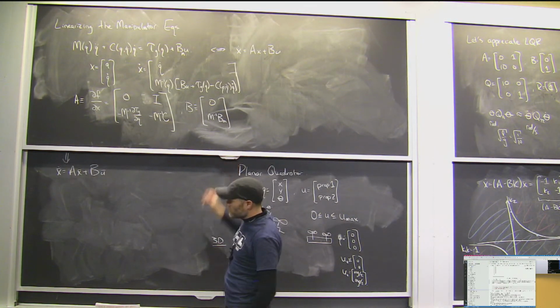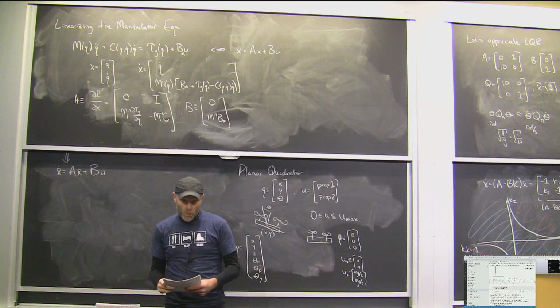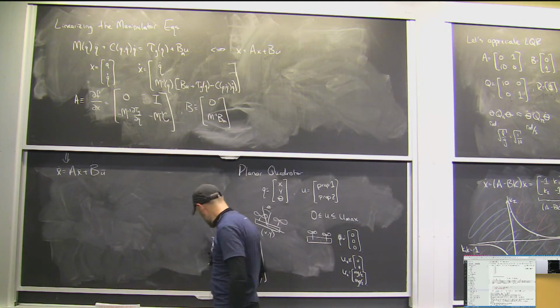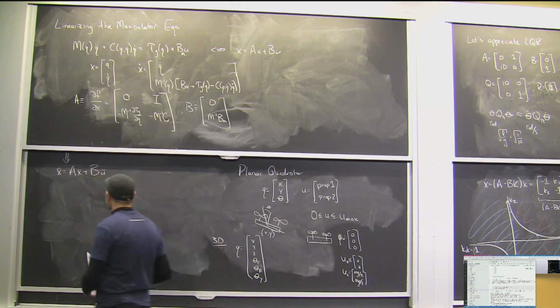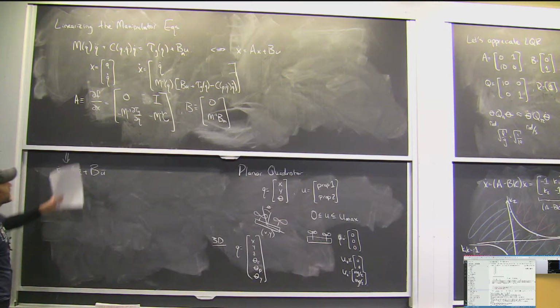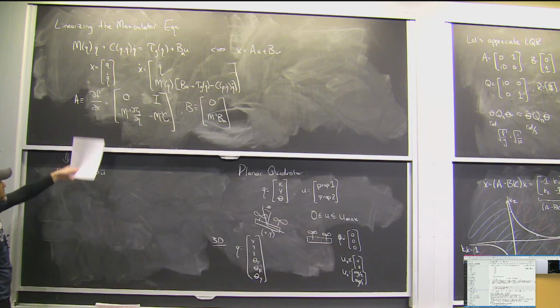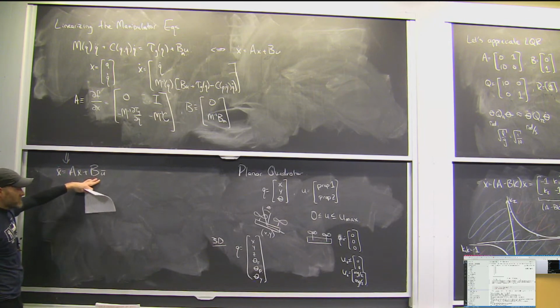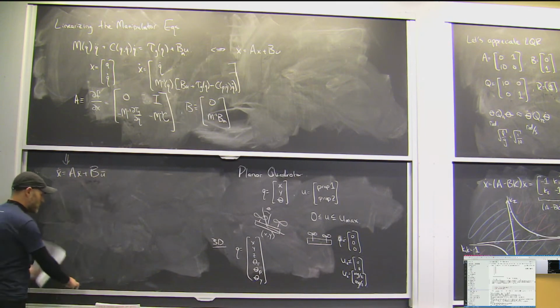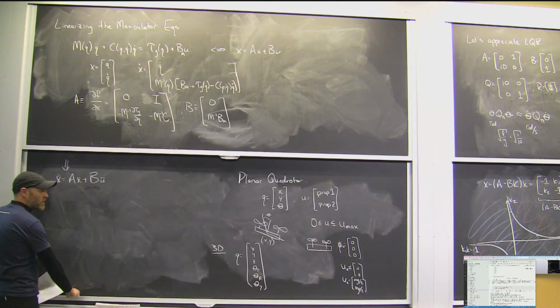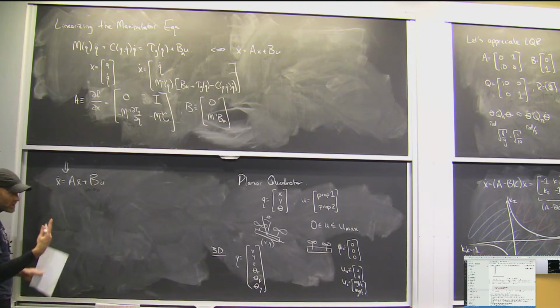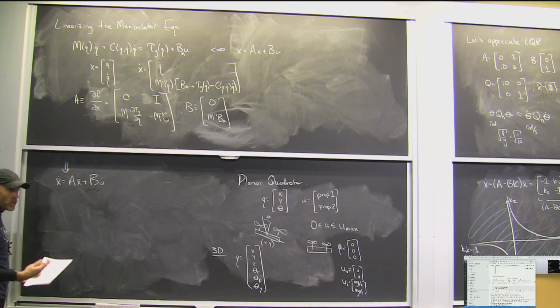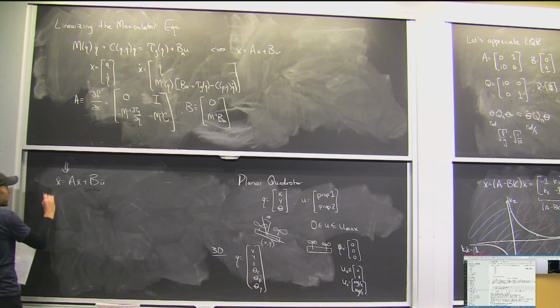Okay, I want to make one last point, going back to when this stuff is going to work. If I can take my manipulator equations and get down to this system, we said that the property that makes LQR succeed or fail locally is related to the controllability of the system. I want to say that more carefully now.